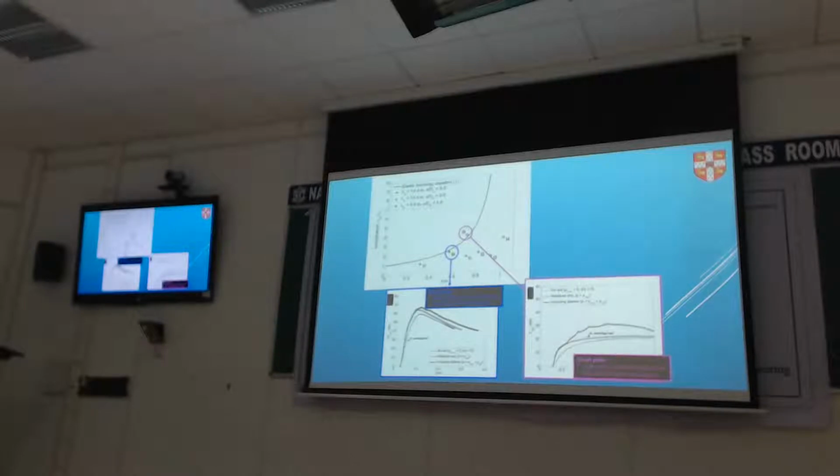You can see this here. This is the pure no soil case, and because we have soil, we are able to reach more. If I consider just the residual value, I'll get this line, and if I consider the dilation also, I'll get quite a high peak. So I can reach about 30 meganewtons, compared to just the no soil case where I'm only at 18. I'm nearly doubling what the pile can carry if I include the soil contribution.